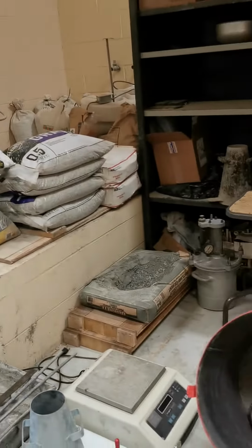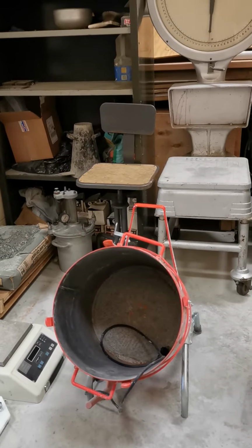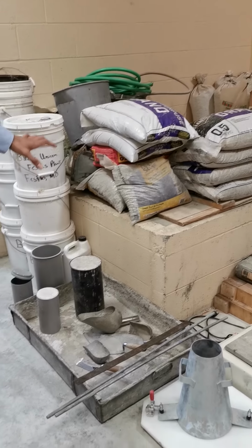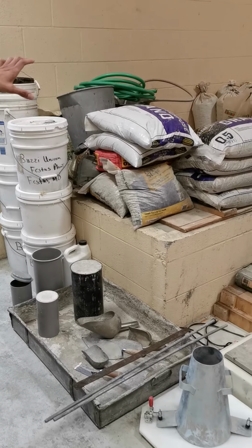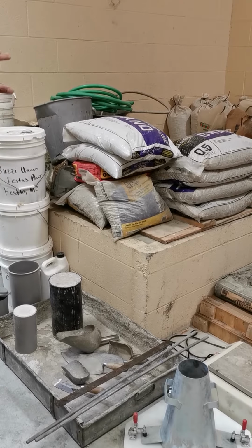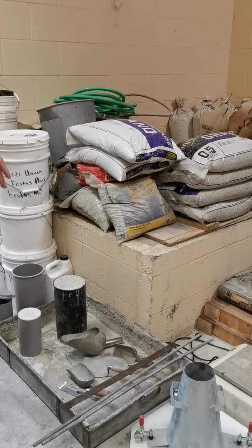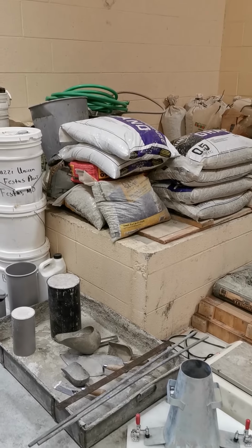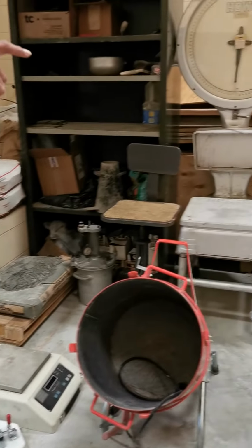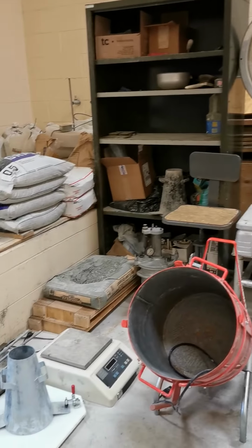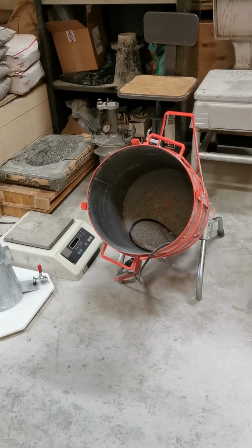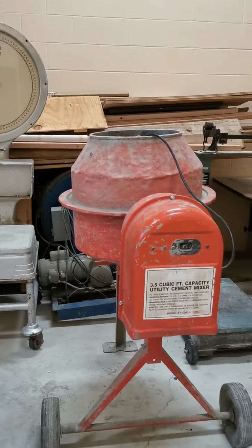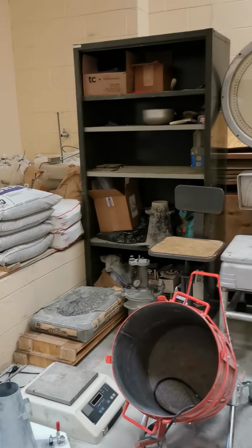The students are trained on aspects of mix design, for example, how to get the coarse aggregates first to saturated surface dry condition, and other such finer points which will make a big difference in the mix design. They are also trained how to operate the mixer, and several students together operate the mixer, and they also adjust the mixing angle as well as the rotation.